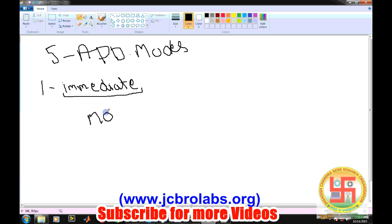If we write MOV A, #25, then in 8051 assembly language the hash defines that the next numeric value is the data. So it will transfer this 25 into the accumulator.